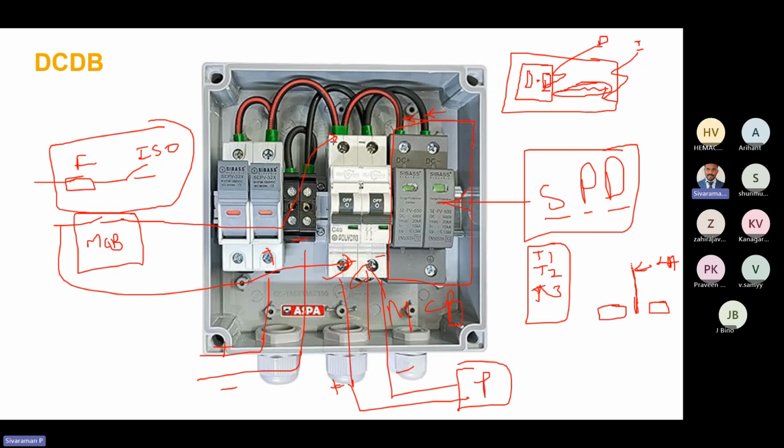For this lightning arrestor there are some calculations, three types. So the coverage will be like this. It means that if any lightning comes into this coverage area, this type of method is called the protective angle method. There is some angle, and based on that we have to work out how many lightning arrestors we need. Under this coverage area, if any lightning comes, this arrestor will capture it and it will go to the ground.